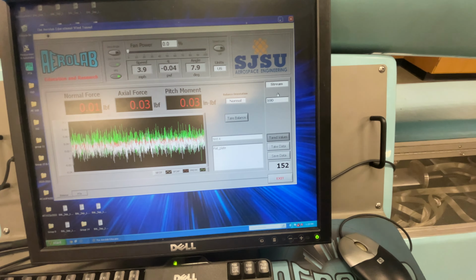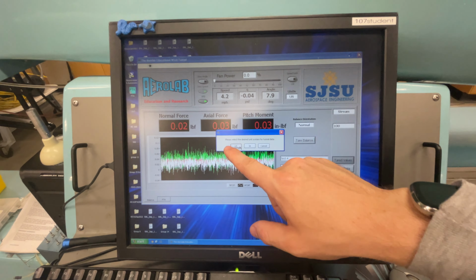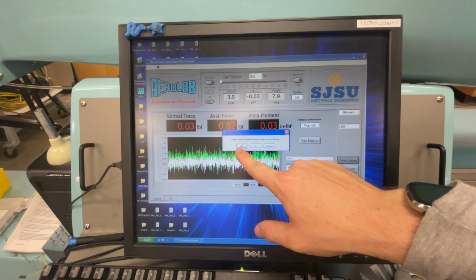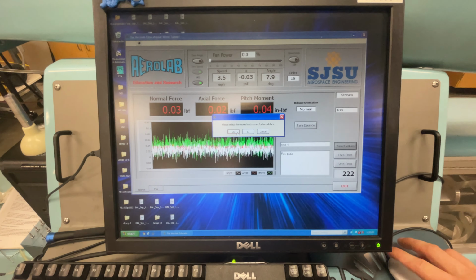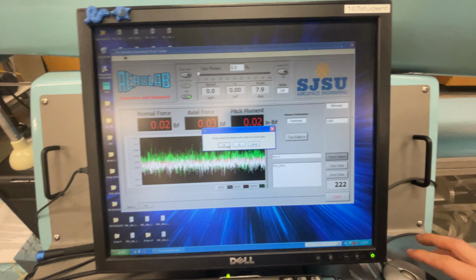If we want to save this data in an accessible format, we hit Save Data, and we can choose either US or SI units. To avoid a bug in the software, we get to use US units. Sorry, you can convert when you do your data processing. Otherwise, if you hit SI units, it sometimes double converts and it'll mess up all of the numbers. If it's in US units, it will at least report them accurately. They're just slightly inconvenient to work with.